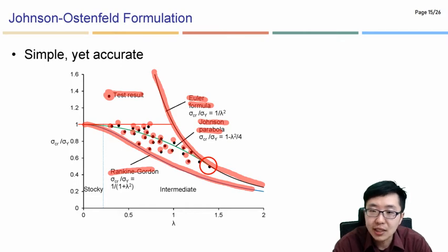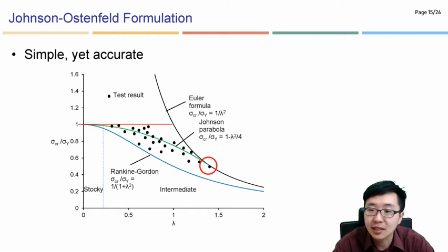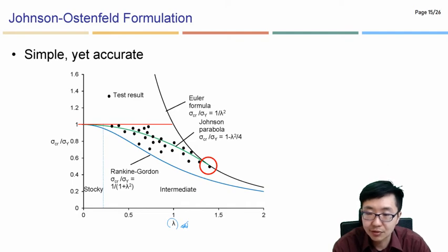One more thing is, as you see here, this kind of testing result, even when we select the stiffened panels or the column geometry as well as material modeling, then we can get the column slenderness ratio. As the column slenderness ratio increases, the stress value decreases, as predicted by empirical design formulas like Euler formulations, Rankine-Gordon, or Johnson parabola. But what I mean here is you can see this testing result is not constant. It is fluctuating behavior. So this kind of single line shape formulation might not be able to predict accurate results.